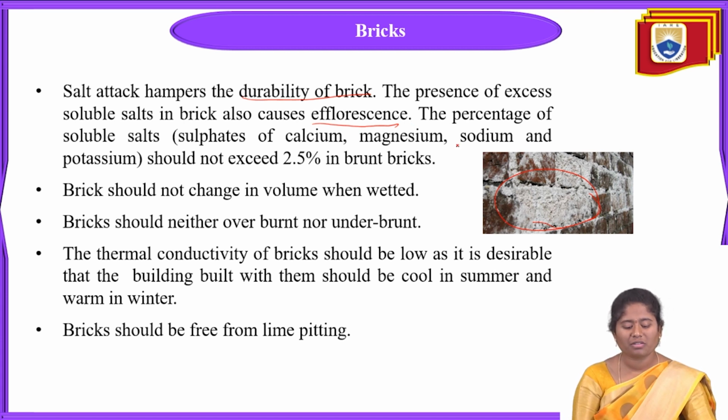That's why the percentage of these soluble salts, sulfates of calcium, magnesium, sodium and potassium, should not exceed 2.5% in burnt bricks.